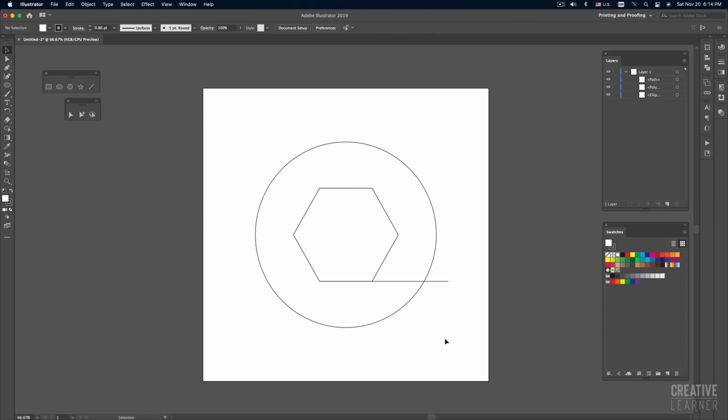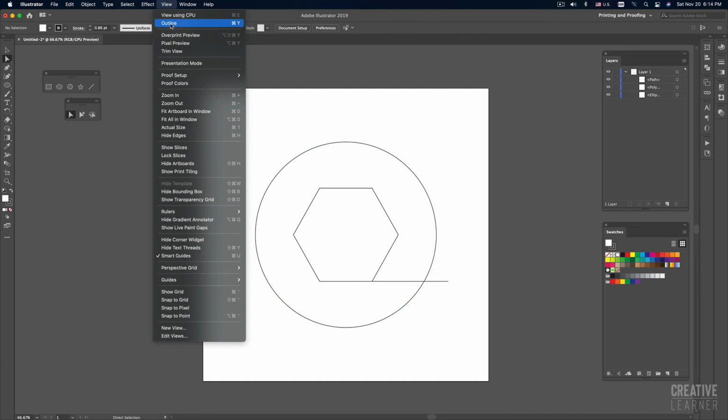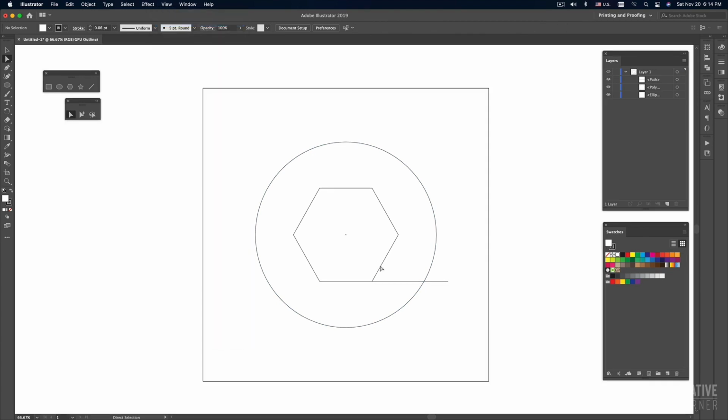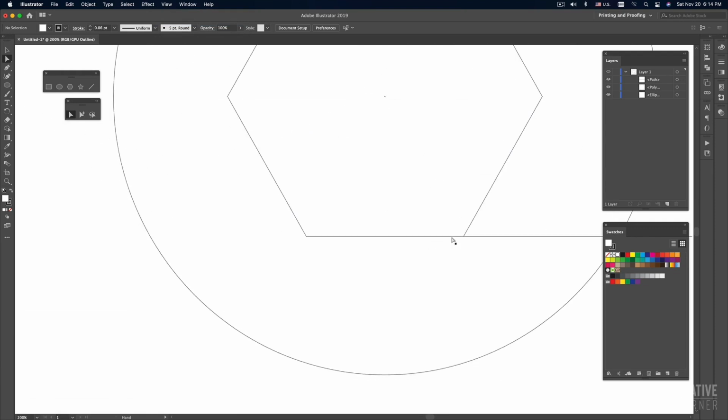So I have one more line. I have already added one more line, and it is very fast and also really 100% accurate. Now if I don't want an overlapping thing, I can just select another point at the back one. After that I can bring it to a touching point. If I want to double check it, I can go back to outline mode, Command Y. When I double check it, I can easily zoom in and check.